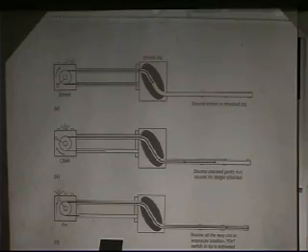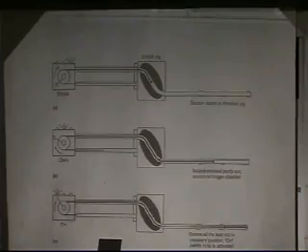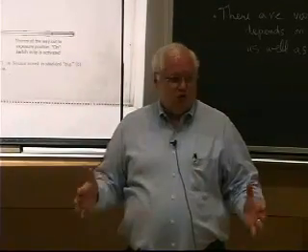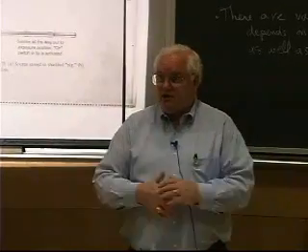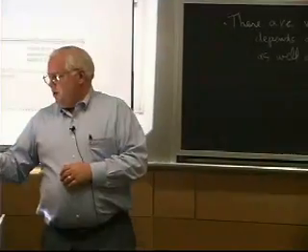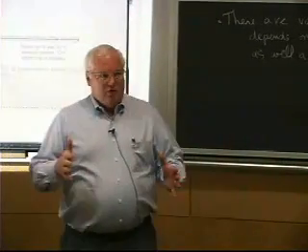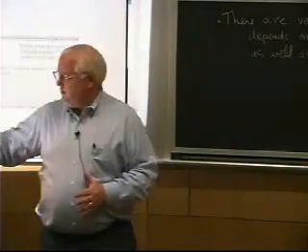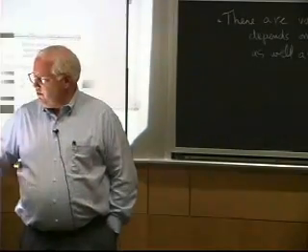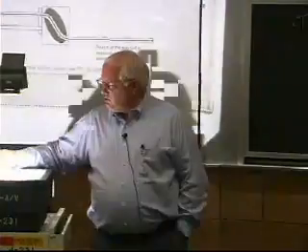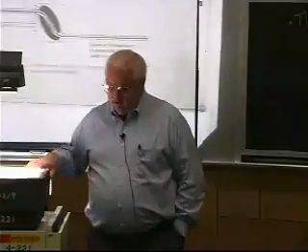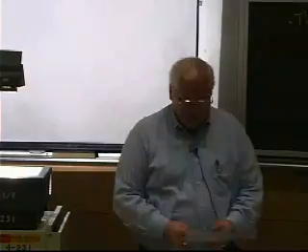For a cobalt-60 source, the thing that holds the source could weigh 1,000 pounds, because you have to have lots of lead shielding if it penetrates that much steel. Typically for Iridium-192, you may have little sources, maybe 100 or a couple hundred pounds, but still, you just push it out there, expose the film, pull it back, and develop your film.